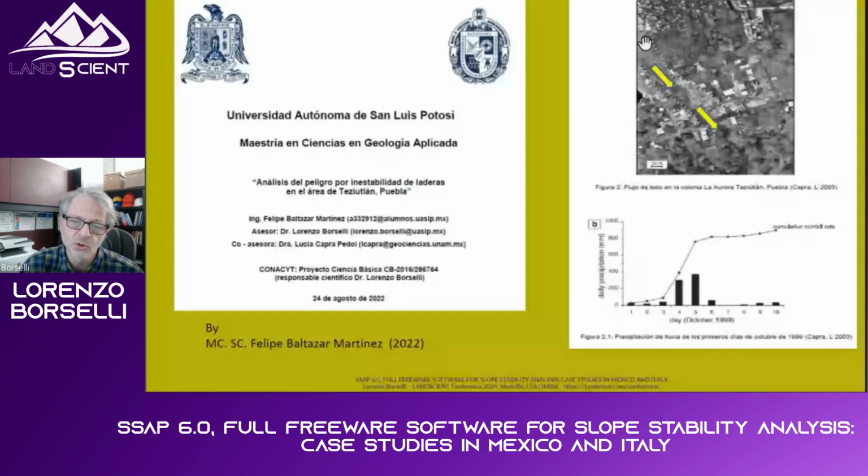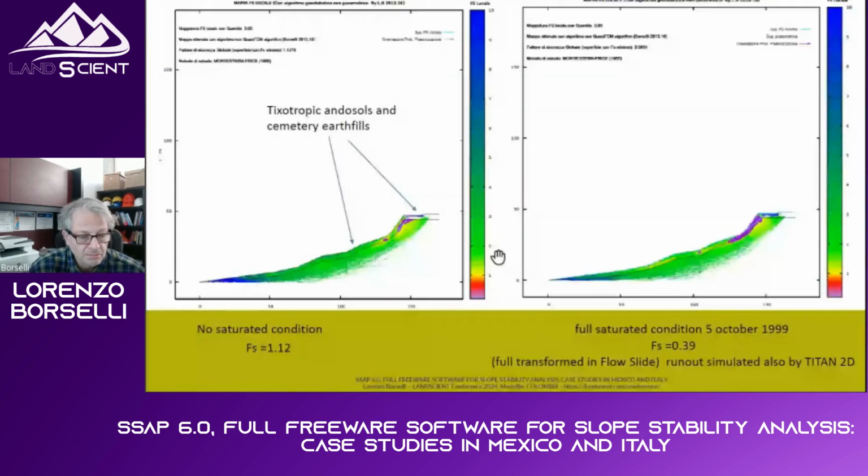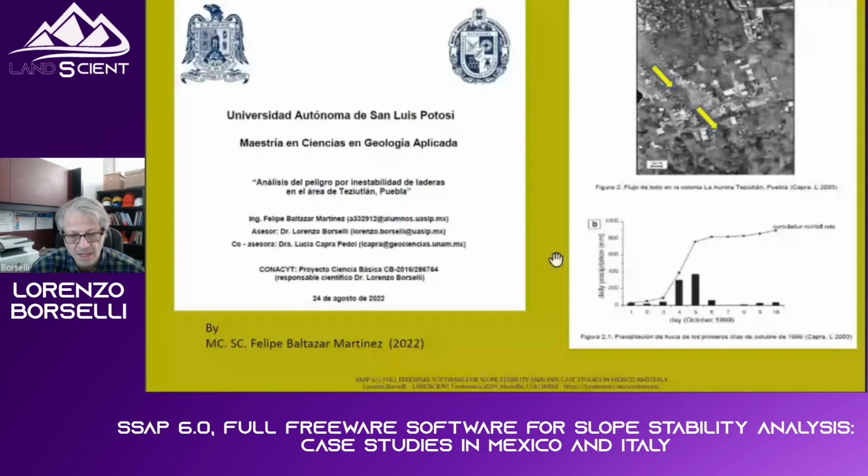This is not an urbanized area, but practically the same, because it's a big cemetery of the county. So this produced a big landslide because of deposits of the materials on thixotropic andosol, cemeterial field, that collapsed after a rainfall of about 700 millimeters in 3 days of accumulated rainfall.